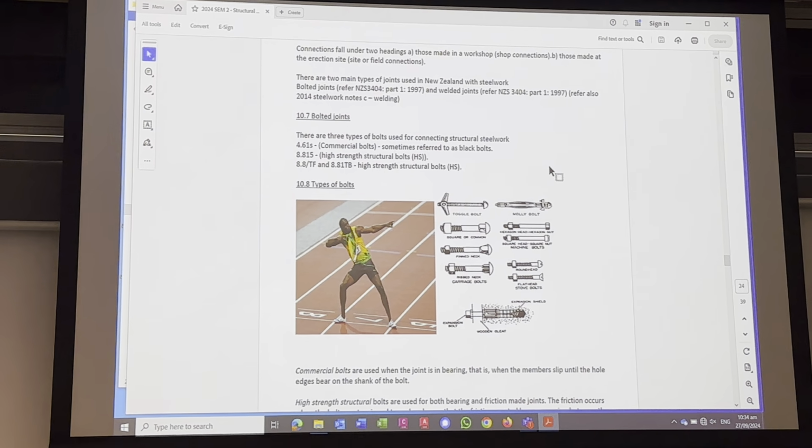And also with bolts, there are bolts that go into concrete. You've got one on your assignment called a Dynabolt. That will go into the concrete hole, and then as you tighten it up, it spreads out. If you look that up on Google, you'll see as you're tightening it up, the top starts spreading out, so it won't come back out of the concrete hole.